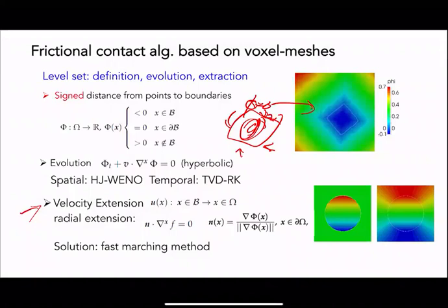Okay, so sometimes this could be mixed with a marker particle method in which we can mark individual particles at the boundary and keep track of how they move and convert the speed functions or the velocity at the boundary, and then we can solve the evolution problem of the level set to update the geometry of the individual particle in each time step.